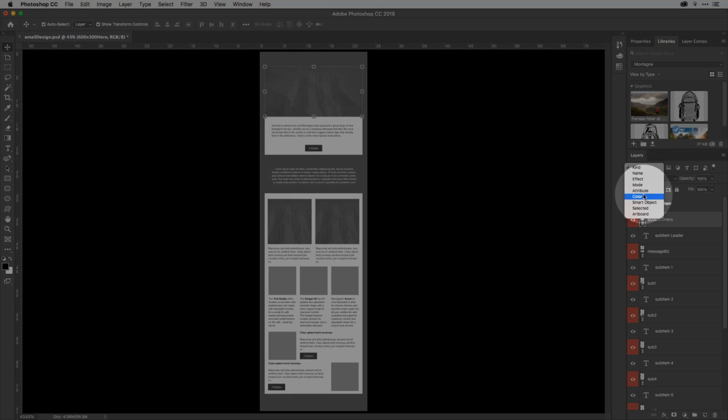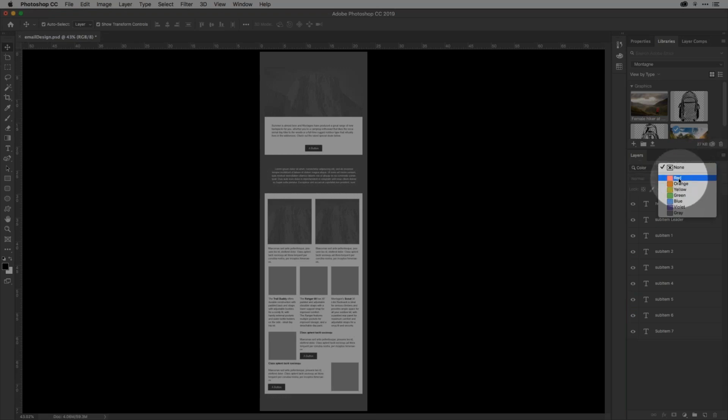So in my scheme here, graphics that can be modified that are smart objects inside of this particular thing are colored red. So what I'm going to do is not go to smart object, because I might have other smart objects doing other things. I'll go to color just here. Okay. And then I can choose the colors I'd like to see. And if I choose red, you can see that it's just temporarily hidden all of the other layers. If I go to orange, then you can see the ones there. They're buttons that are colored orange in my scheme. And it's a good idea to work out a display scheme for these things thinking forward. And when you want to turn that off, you just hit the toggle over here.